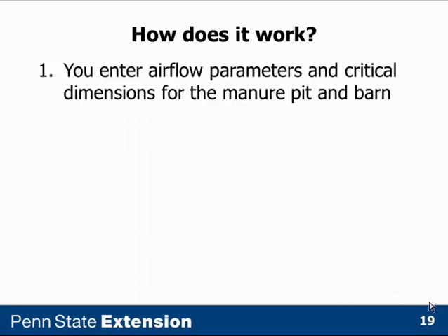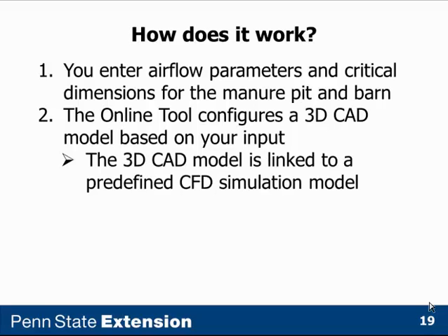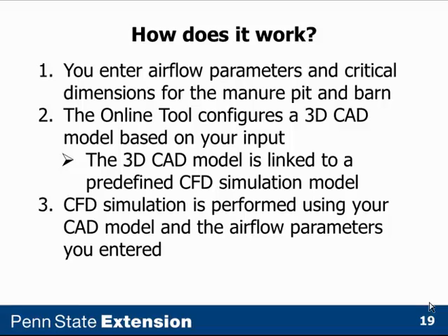You input the critical dimensions of the manure pit and the barn. The online tool configures a CAD model based on your inputs. Then it's linked to this CFD simulation model. The CFD simulation is performed using your CAD model and the airflow parameters that you enter.